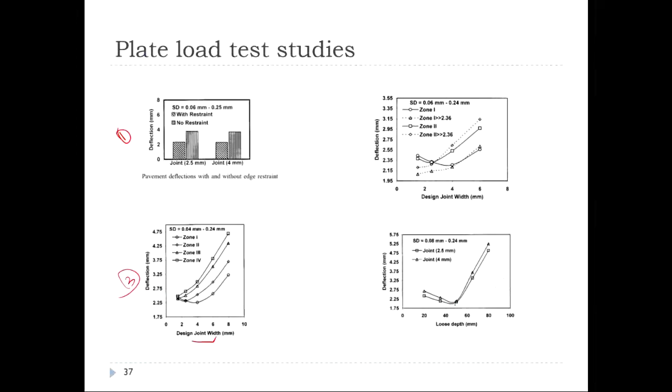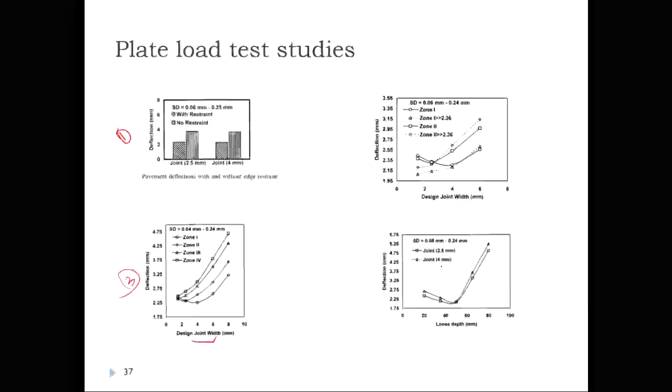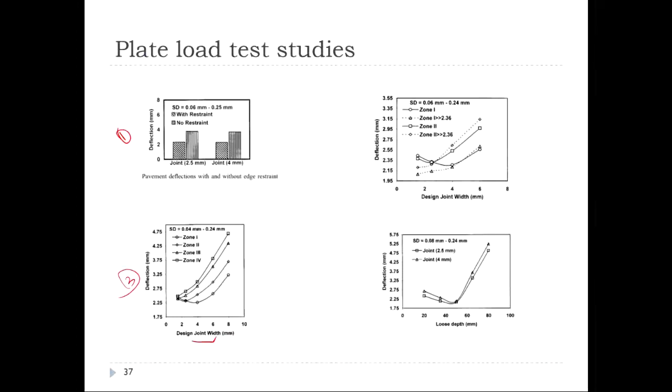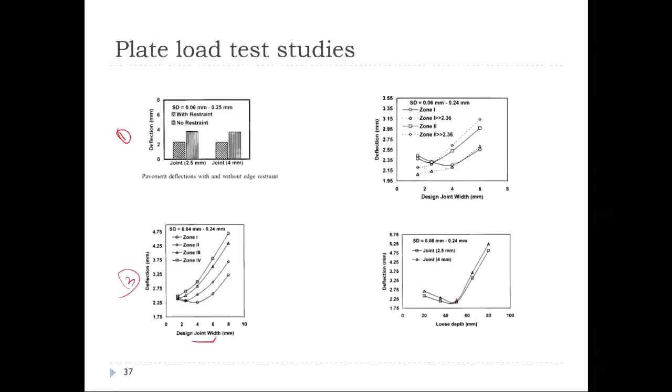If you provide a higher bedding sand thickness, of the order of 60 mm, 80 mm, as I told you, these are sand. You will find difficulty in compacting sand if you go for thicker layers. So there is an optimum thickness of the bedding sand, beyond which you will find difficulty in compaction.